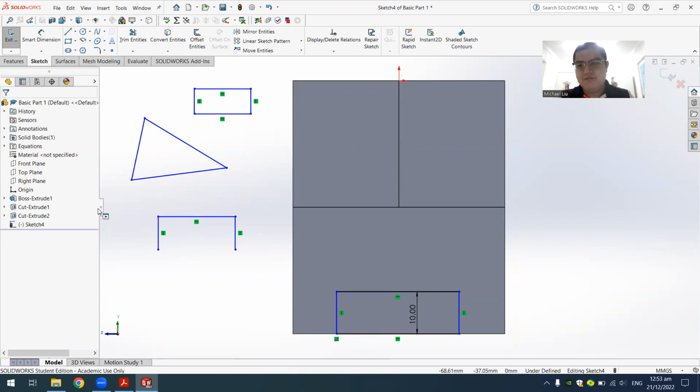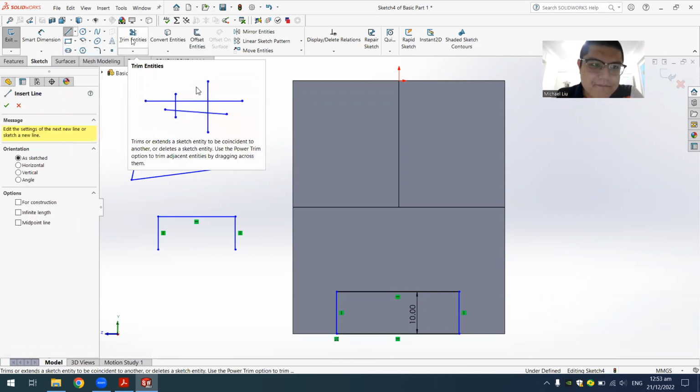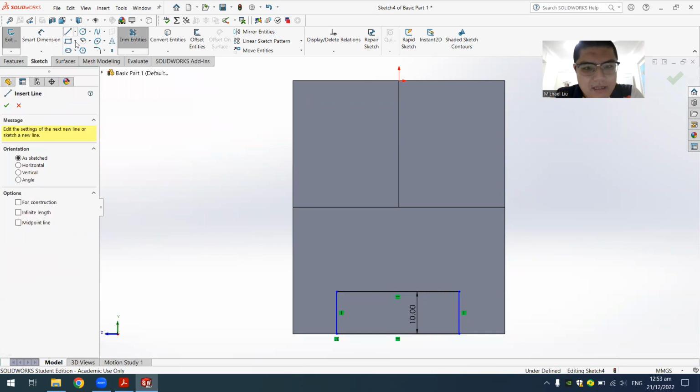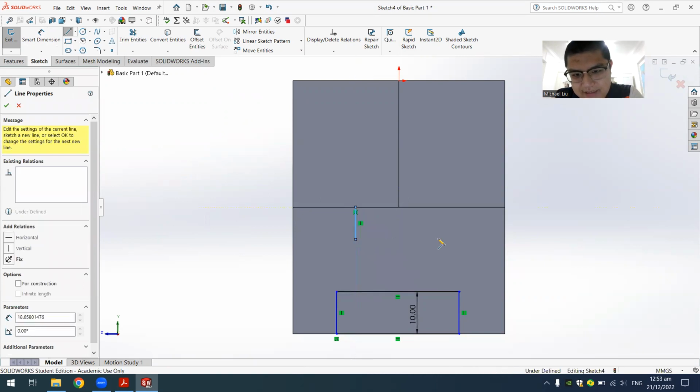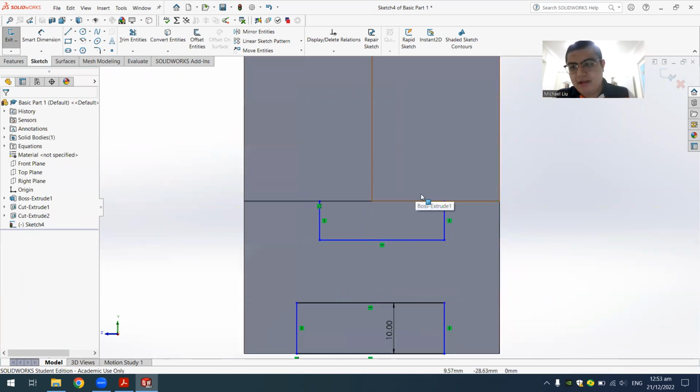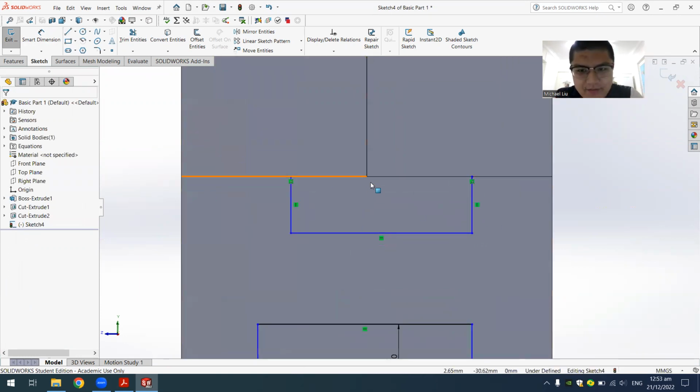So in SolidWorks, if you want to extrude or revolve or add some features to an open sketch, usually it will fail. Unless you draw it in a specific manner. But in this case, we just assume it will fail. So for example, let's remove all this. I noted that some of you actually draw this rectangle something like this, and went to extrude it directly, and of course it will fail. This is because this is actually an open sketch.